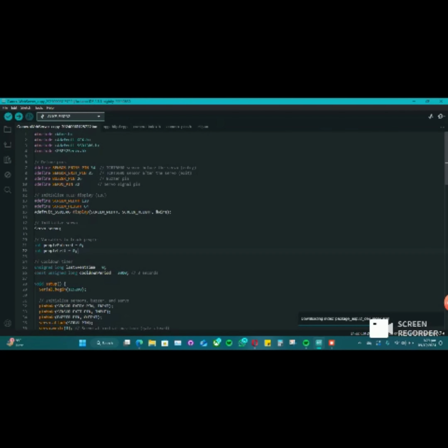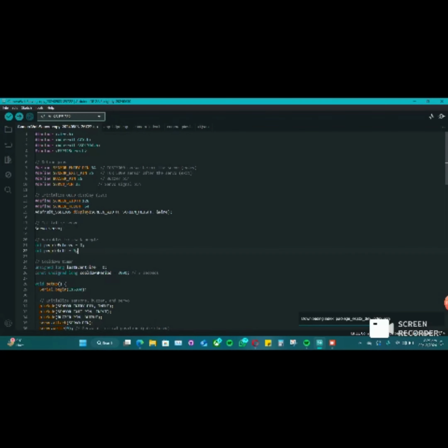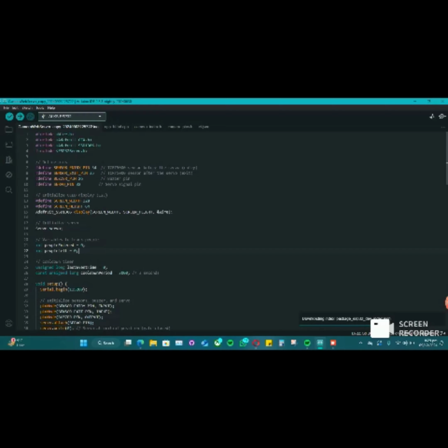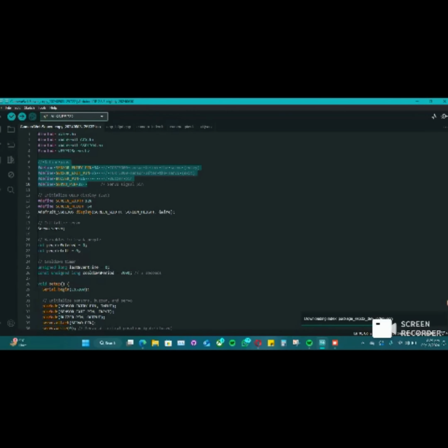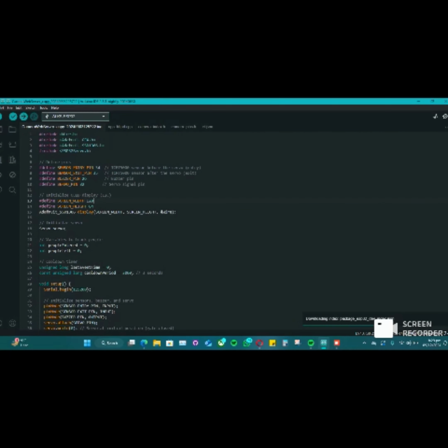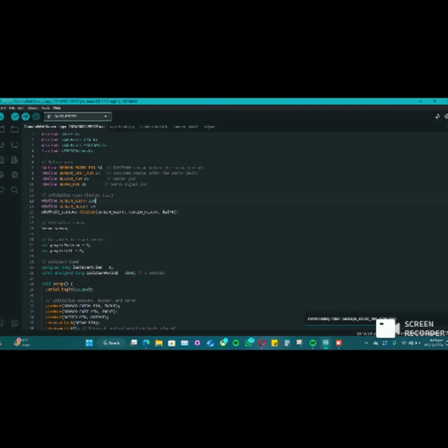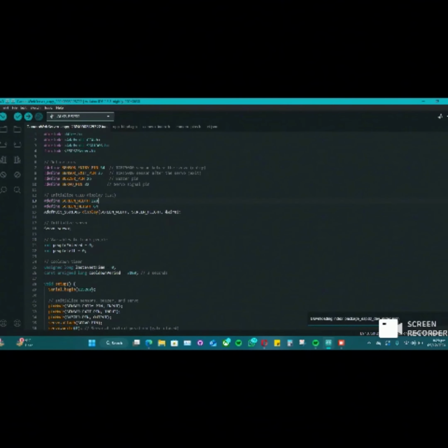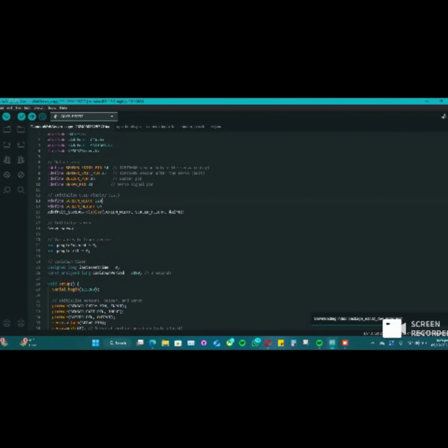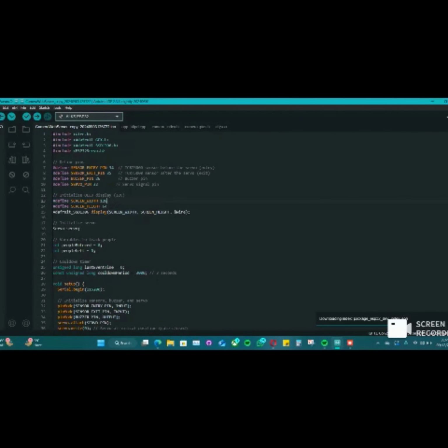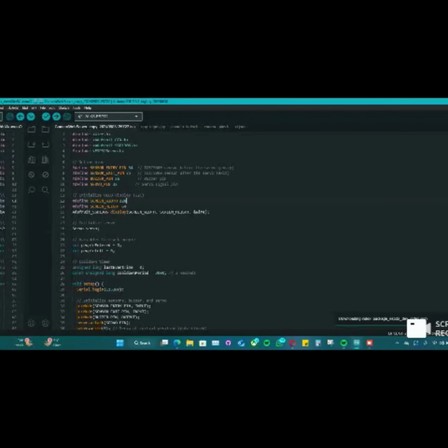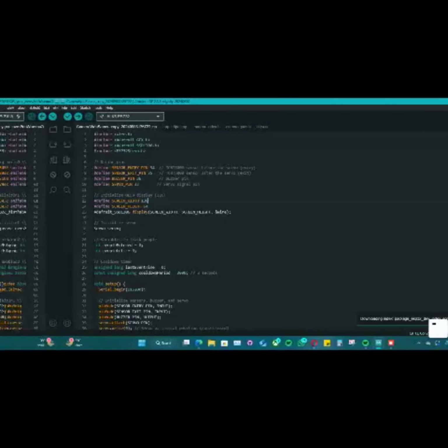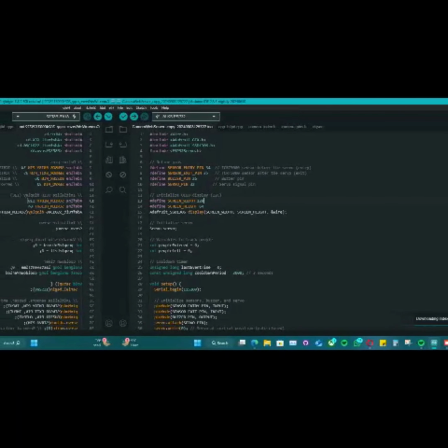the gate. Next up, we defined our pins upon which we have attached our different sensors, the buzzer and the servo. And afterwards, we'll initialize the OLED display by defining its width, height, and the function responsible to take in input and display a certain output later on, and then a function to initialize the servo.